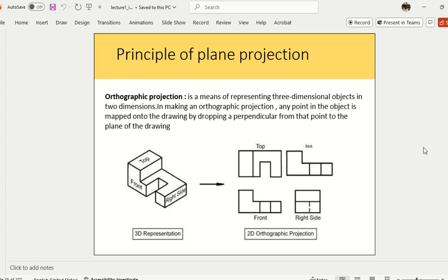But I want to show my client or my contractor that there is some line behind which you cannot see. So I'll make it with a dotted or dashed line. A dashed line represents something which is behind, hidden. It is there, but you cannot see it from here. Got my point? So right hand side, this box, and I have to show this line as well, right?